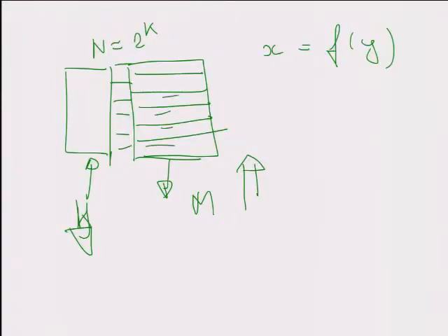and you compare it with all the data that's stored in memory. And if you have a match, if they are identical to each other, you raise this line here. So there might be a 1, 0, and all the other ones 1, 1, and all the ones 0. That's where you have the match. And then you translate this into an address. Right? Instead of a decoder, you have an encoder. It goes from 2 to the k to k bits. So this only works when you have a perfect match. All the bits are exactly the same.